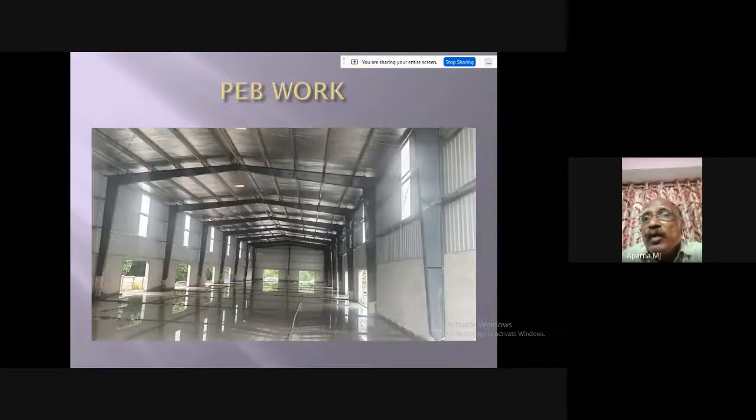So in the steel building, you see the panels are erected here. You can see the roof panel resting on the purlins. The rafter is there. Columns are there. Outside the column, there are some panels, and at the bottom level, some block work, and it is plastered and painted. At the other end of the wall, that is known as the gable wall, there also the panels are erected, and you can see two doors are provided in the gable wall, and there is a center support at the gable wall. There is a column at the middle.